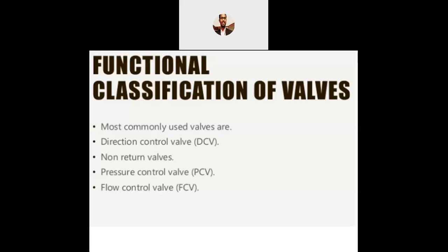This is majorly important in order to avoid what? Cavitation. In order to avoid the cavitation, non-return valves play a vital role. Without these non-return valves, every day you have to fill it manually and then start the pumps. That should not happen. So non-return valves play a major role in avoiding the cavitation. In other words, it also extends the life of a pump. So these are all the non-return valves, then the pressure control valves, and obviously the last one will be a flow control valve.